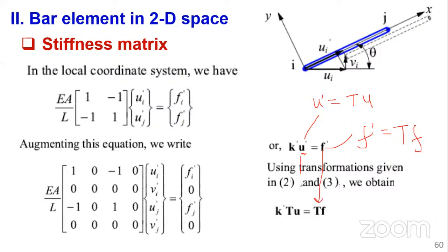This is this, and this U is this. If you look at this carefully, we are pre-multiplying the transformation matrix with F. The order is very important. Otherwise, you might interchange and then you find they are not compatible. I remember I told you from lecture 1 that you should revisit matrices because you do a lot of matrix operations here. That's why sometimes this course, in some books, is referred to as matrix analysis of structures. Now, remember our form of finite element equation is F is equal to KU.